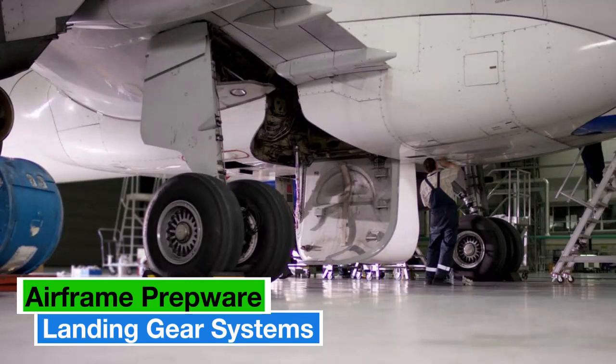What action, if any, should be taken when there is a difference of more than 5 pounds of air pressure in the tires mounted as duals? Correct the discrepancy and enter in the aircraft records.